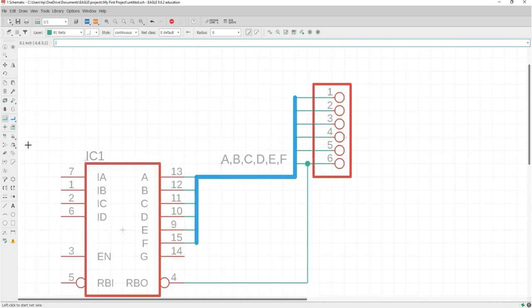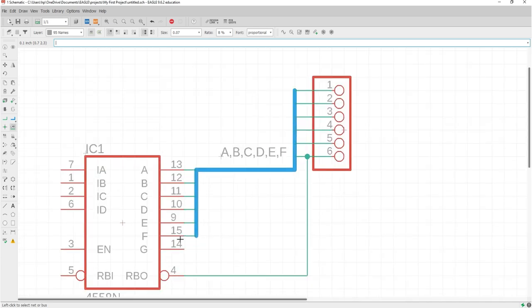This is a label icon. It is used to place the name of a bus or nets as a label. Labels cannot be changed with the change text command, but rather with the name command, because the label represents the net name. The name command is used to give names to components, nets, or buses.